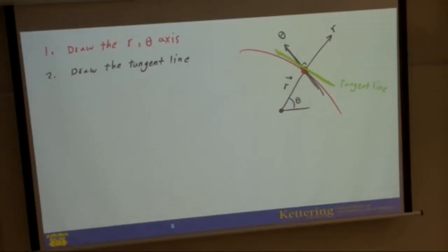Next step, you need to draw the free body diagram. To draw a free body diagram, these are the forces that you have to show in this coordinate system. First one, normal force, frictional force, weight, and applied force. I use P to show this one is an applied force.